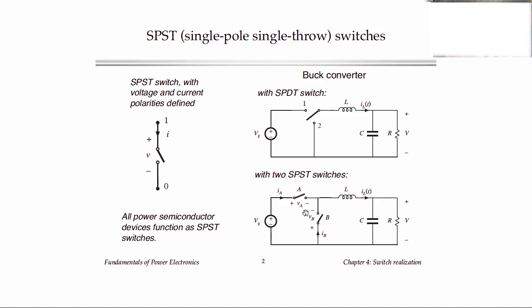The other case, where both switches are off at the same time, can happen, and it completely changes the characteristics of the converter when it does. And so we're going to talk about that case in Chapter 5 and see that it leads to the discontinuous conduction mode, which is something we haven't talked about yet, but we need to.